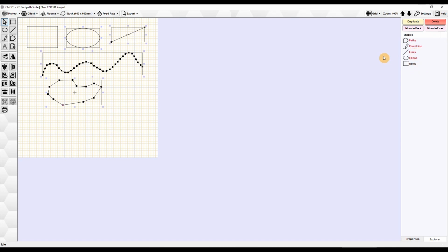Now, any particular shape, you can choose to arrange the orientation of the shape in here. So the way that it works at the moment with our current G-code engine is we are going to be doing a particular shape based on the order with which they appear in here. So the one that's closest to the top is the shape that will actually be done first.